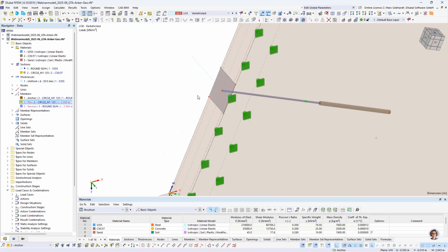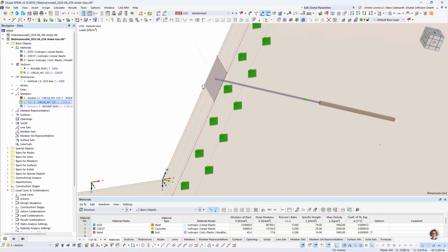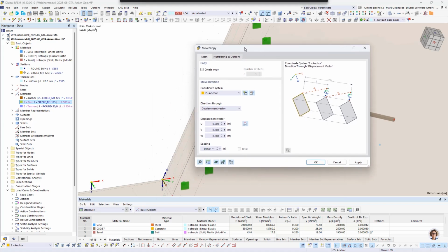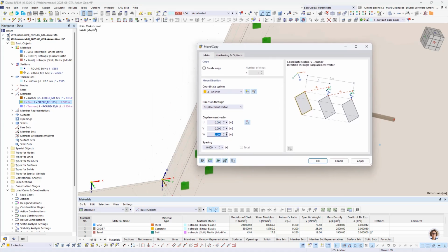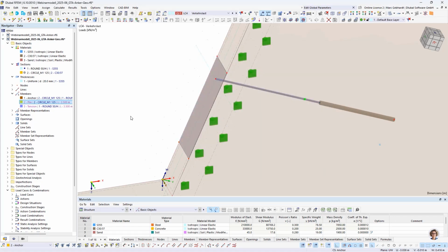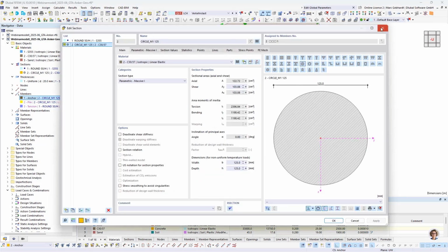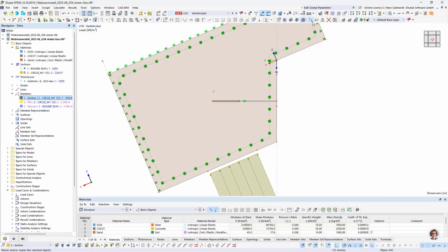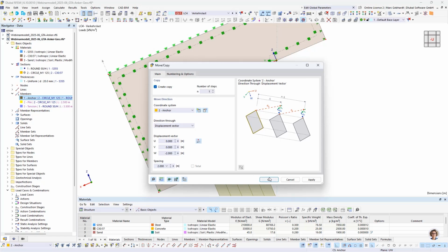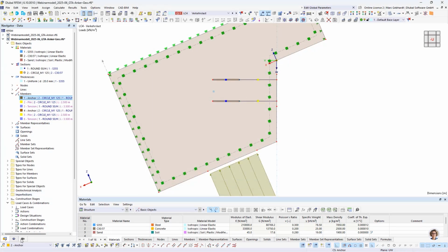Now it's got the anchor, and we want to do a second one, so selecting these nodes, and again the distance between the anchors will be 2 meters in minus V. Get a 3 meter plate, and also copy. Oh, that's interesting. Now we can also copy them by selecting the anchor in the navigator. Also 2 meters. Copy. Now our anchors are finished.